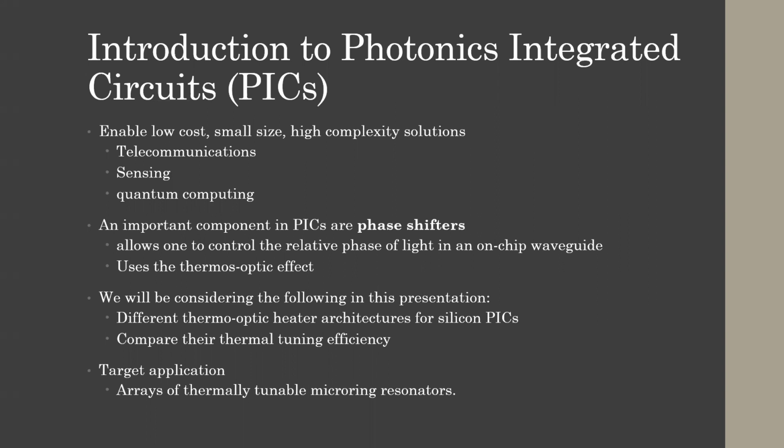For silicon PICs, phase shifters typically use the thermo-optic effect, by which the refractive index modulation, and therefore phase modulation, is related to the temperature of the waveguide. In this presentation, we'll be considering different thermo-optic heater architectures for silicon PICs, and we'll be comparing their thermal tuning efficiencies.